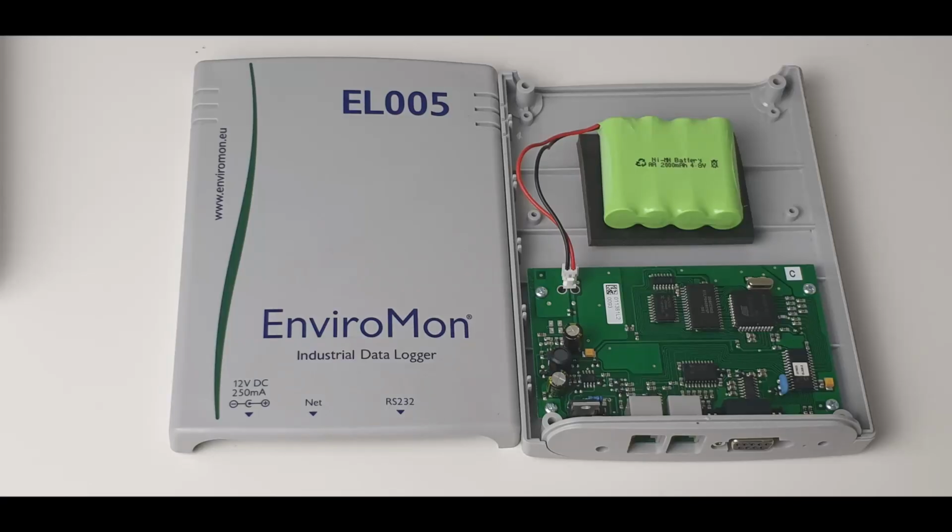The EL005 data logger has an internal battery backup. At the time of doing this video, it's a 4.8 volt 2000 milliamp rechargeable NiMH battery. Now this hasn't been the case in the past, but most likely if you bought the logger in the last 6 years or so, it would have been. When the loggers were first introduced, they used a 600 milliamp rechargeable battery. In any case, the battery has a limited life and will diminish over the years. So if your logger is a few years old, it might be worth looking into getting another battery, and we can help you with that.